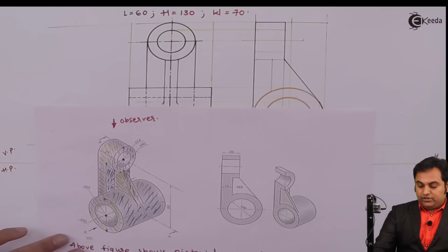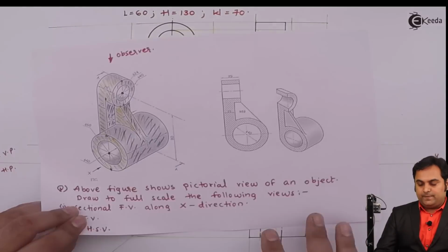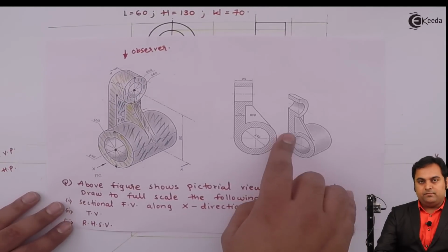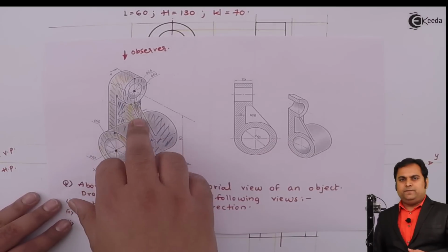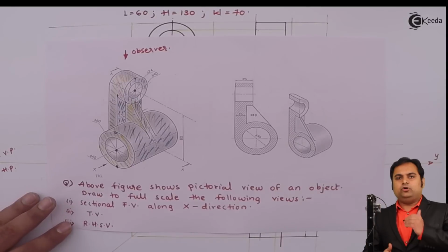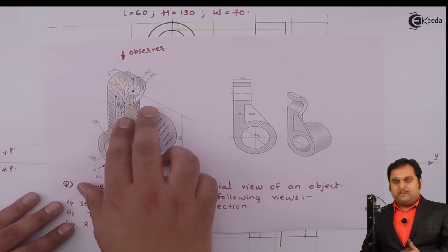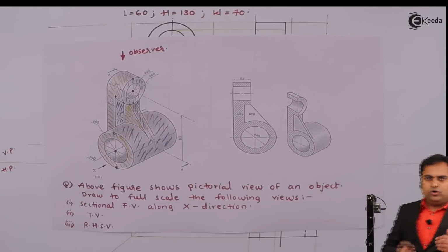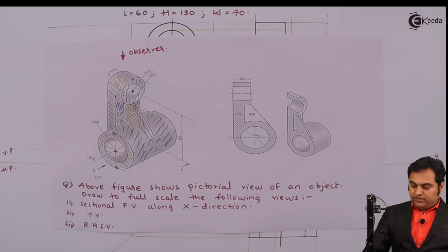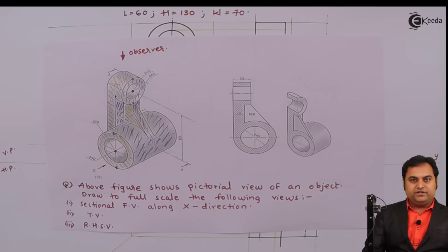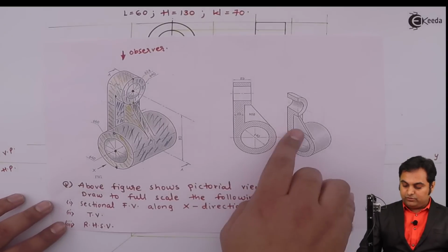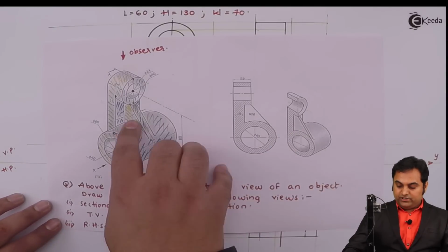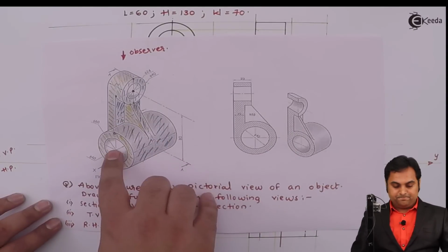Finally, here when the rib is cut, if we see, the width of the rib is 10 mm, and remember this point, whenever the rib is cut into two halves along the width, in that case sectioning won't be there on the rib. So here the rib will remain plain, and then when it goes down, it cuts this cylinder, and when the thickness of the cylinder is cut, the sectioning will be looking something like this. So here I'll draw the surface in this way.